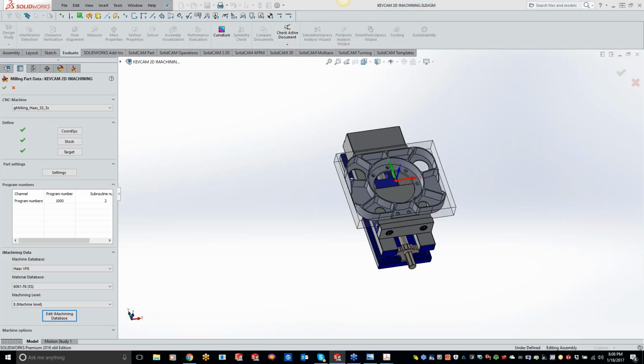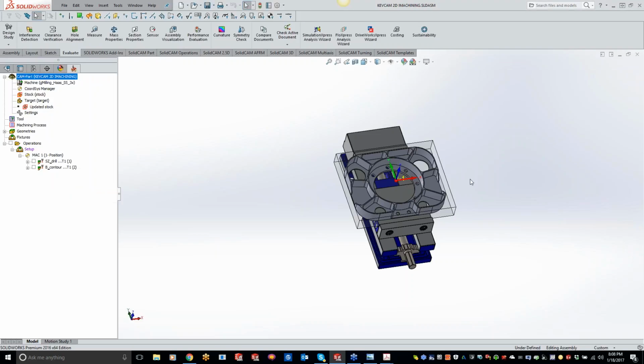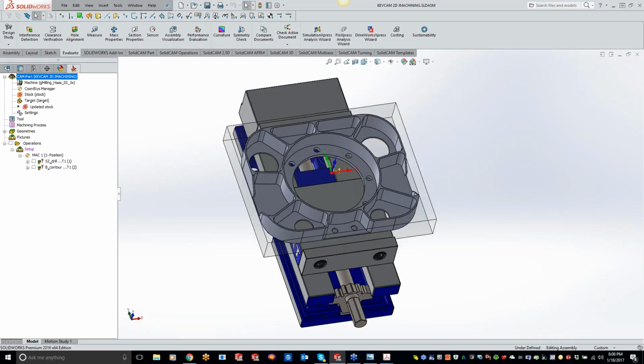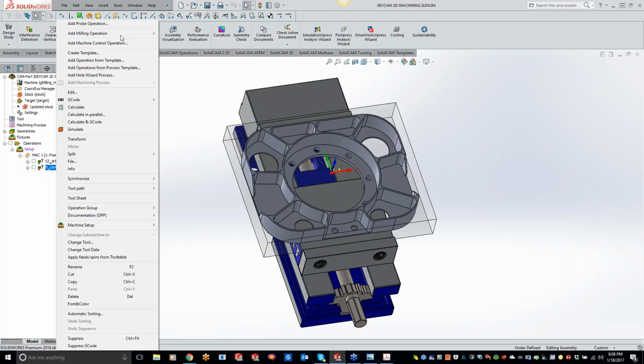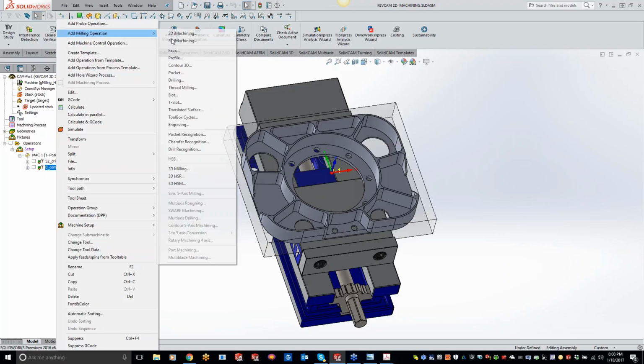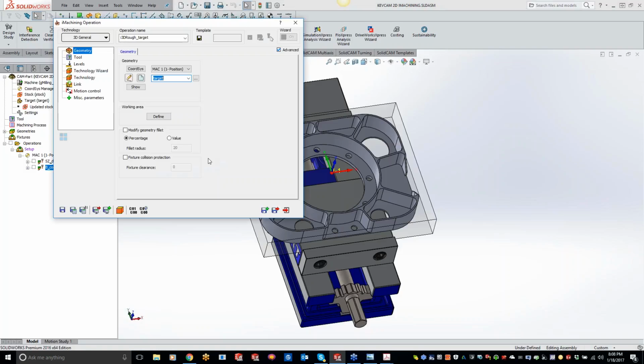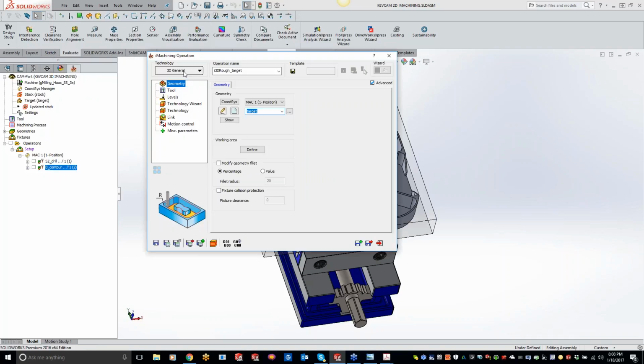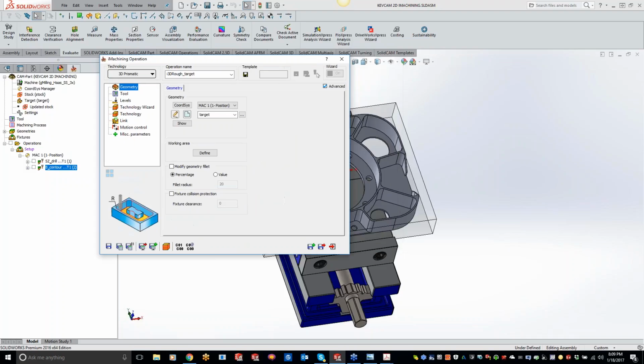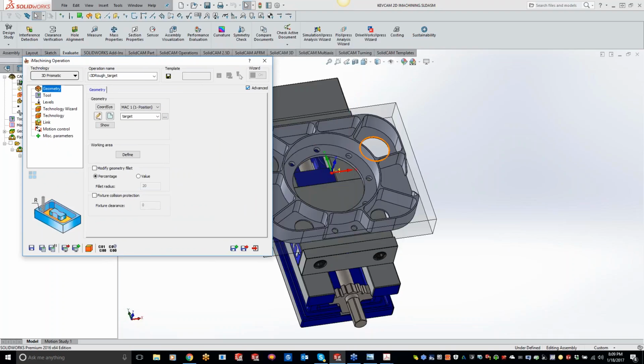Okay, so like I said, basically taking the part that we had last week here, and now we're going to go into easy mode using 3D iMachining. You'll see that I already have my part probed up right here. So we'll come into our 3D iMachining now. Now we have 2 different options inside 3D iMachining. We have 3D General and 3D Prismatic. The difference is for your 2.5D parts, you're going to want to use the Prismatic. It's going to pick up all your flat floors, flat walls, all that stuff.